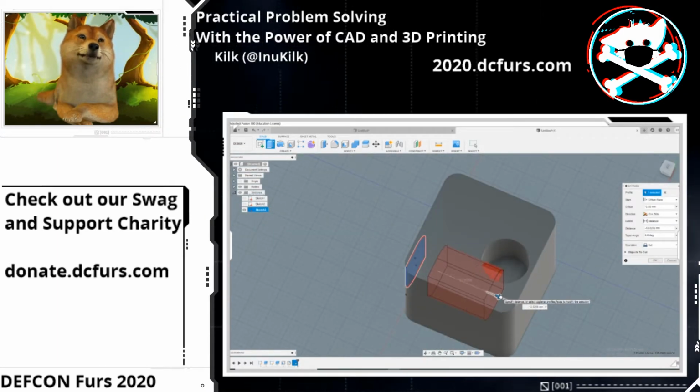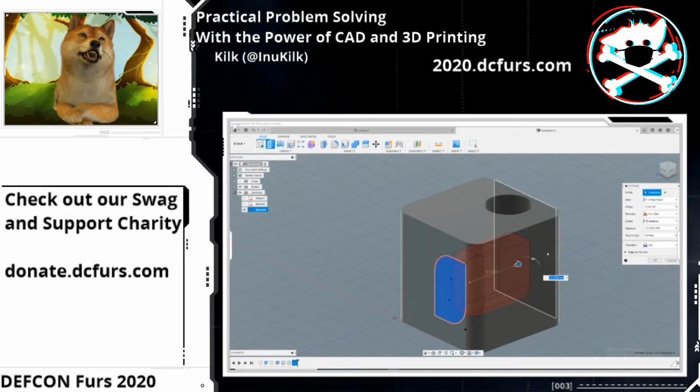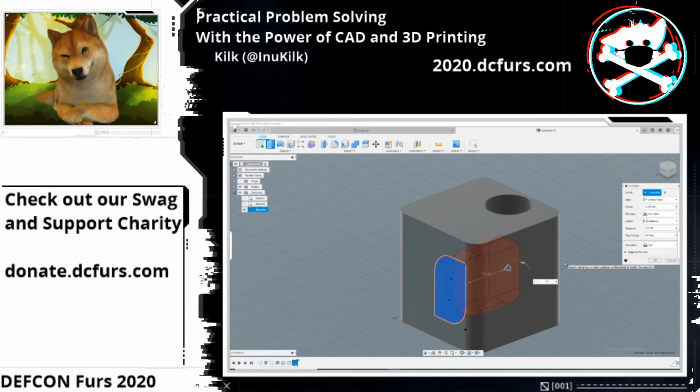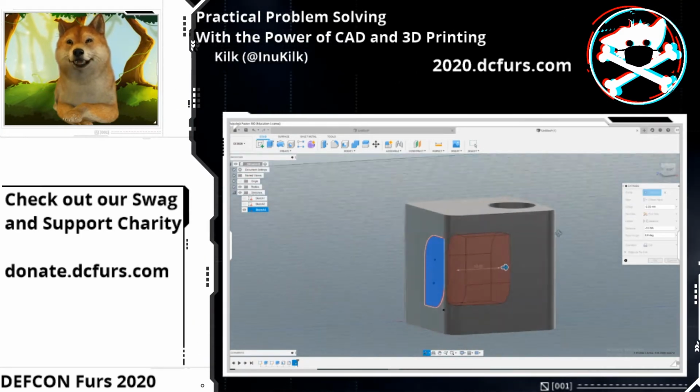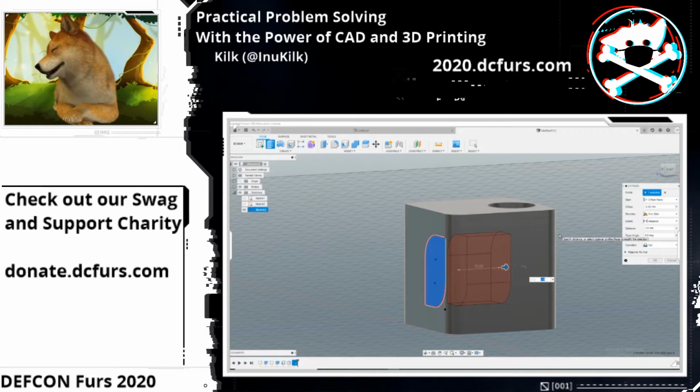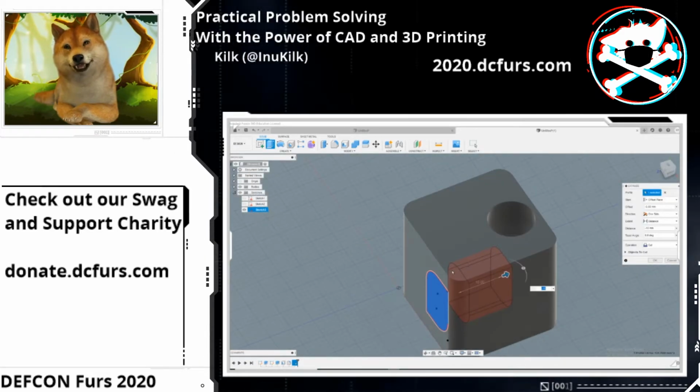You can't see that, can you? Let's just do that. So you see this? It's going to do an extruded cut, and I'm going to make that -10. Well, you see that? Yeah, there we go. It wasn't showing it earlier because there was no way for it to be perceived, because it would just be inside of it and you wouldn't see it at all. So basically what we're doing is we're taking the sketch here, and with the offset plane, we're taking the same one, but we're moving it -10. And then based off of that sketch, we're now doing a profile plane on the offset. And so now we have this.